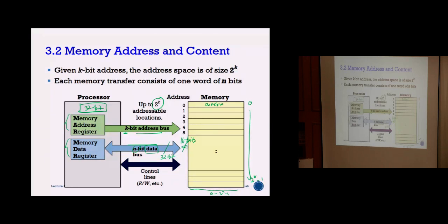Each time I want to load my register with a value from memory, I need to do 2 cycles, because each time my data bus can only hold 16-bit data. So even though it is possible to mix and match different lengths of bus and memory, if you match everything, then your life is easier. If your processor is 32-bit, then your processor's data bus is also 32-bit, so you probably want to interface with a memory that also supports a 32-bit data bus.